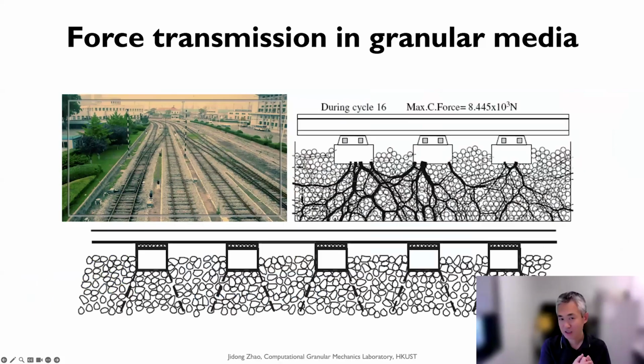And this is the application that I want to relate to the previous railway station here, and how we can evaluate the performance of the railway tracks, the ballast supporting these railway tracks. We can really use DEM to simulate such a supporting structure and to evaluate or assess its performance subject to this repeated train load here.